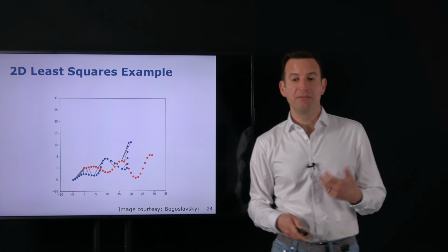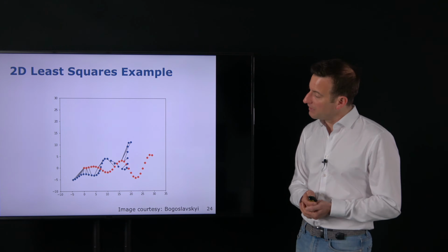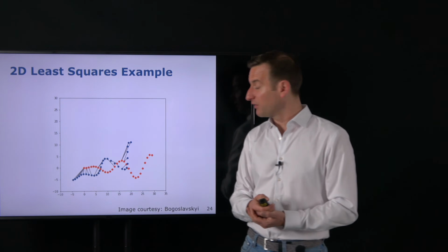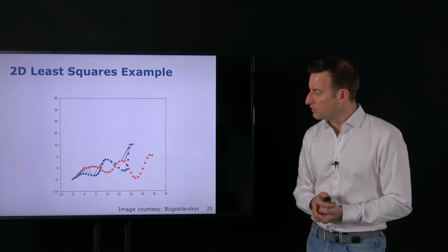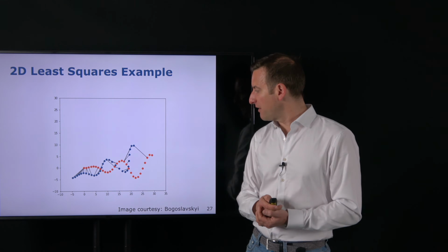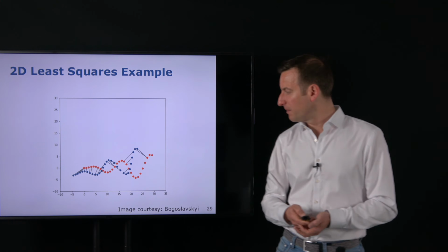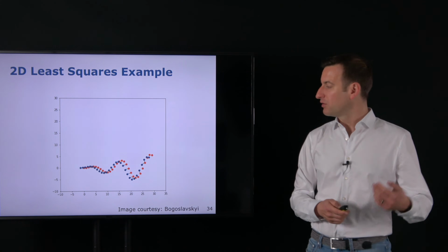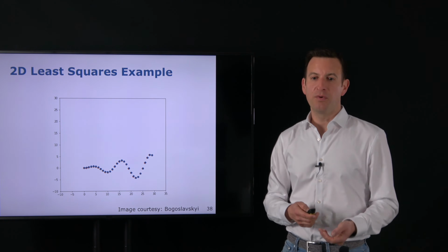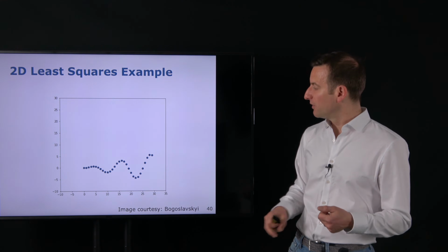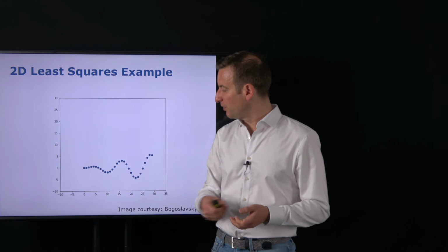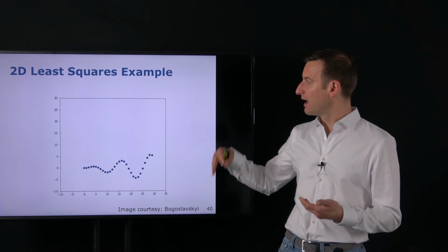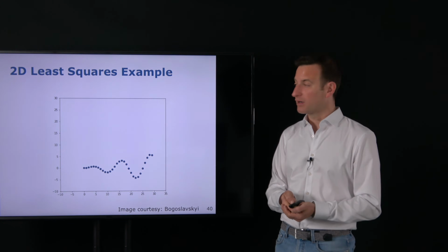I'm ending up in this configuration, and then I'm repeating this process again. I'm re-estimating my correspondences, how the new correspondences look. I compute my alignment, and in every step you can see some of the correspondences will change, and we very slowly go a step forward until the 2 point clouds are finally aligned. In this case you can see both point clouds overlap perfectly, so we have found the transformation which aligns the original point set with our target point set.